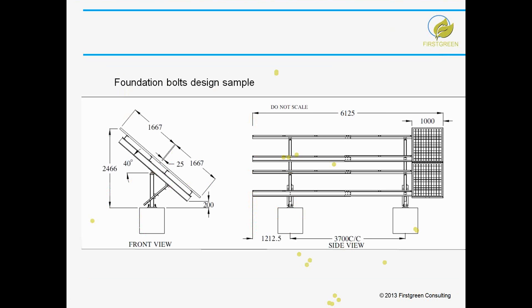when you start, you will first be asked how to select your structure. Again, there are various options, as I discussed previously: the structure can accommodate a portrait layout or a landscape layout. You have to see how much the pitch should be and how much the tilt angle should be, which will be taken up by Suhas in his presentation.